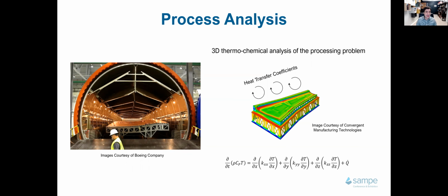In this case, you can either use a traditional experimental approach by placing thermocouples, do thermal profiling of a part, and look at the temperature history of the part to make sure it is within the bounds and limits that are identified by process specifications. You can also do what is known as process simulation, where you will use things such as finite elements.